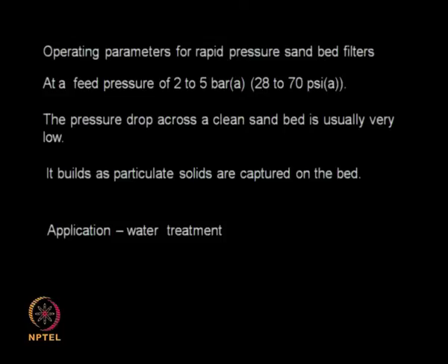Generally if the entire sand bed is very clean, the pressure drop will also be minimal, but over a period of time, if you are accumulating waste material, or if biological growth takes place, then slowly you may find that the pressure drop across the filter increases. At those times you may need to wash these sand filters. So as I said, they are extremely useful for water treatment applications.